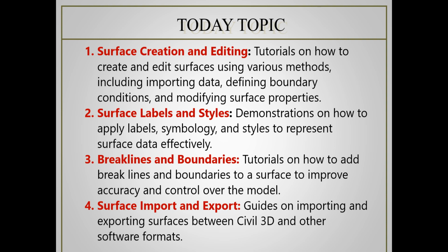Second, surface labels and styles. Demonstration on how to apply labels, symbologies and styles to represent surface data effectively. The third, I will explain breaklines and boundaries: how to add breaklines and boundaries to a surface to improve accuracy and control over the model.